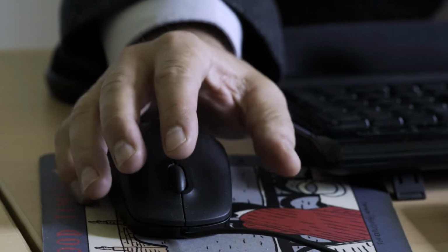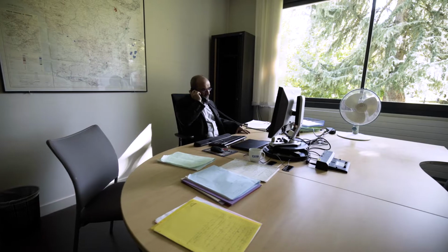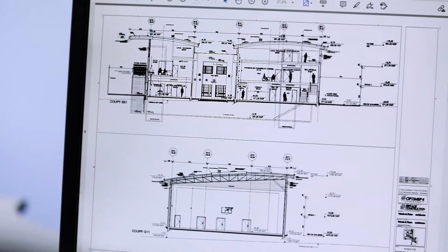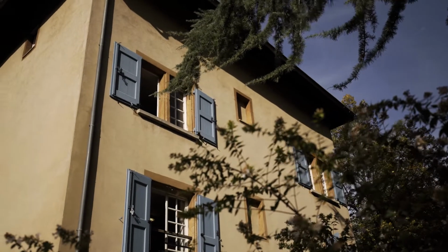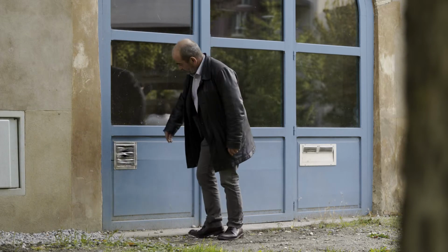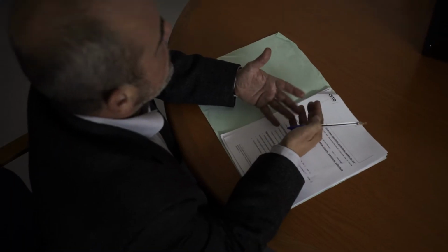Based on the prior information collected concerning the building, year of construction, description, plans, photos, sketches, possible renovations or refurbishments, an on-site visit will be carried out. The purpose of this visit is to confirm this initial information, to deepen the knowledge of the building, particularly with regard to potential radon entry routes and its ability to integrate appropriate corrective actions. In this context, it will be appropriate to have an exchange with the owner in order to review all the relevant elements of the building.